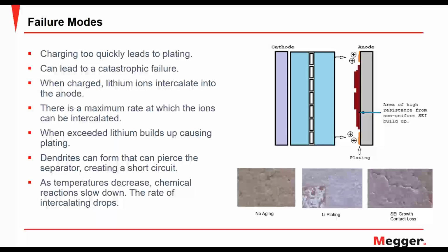This formation is caused by maybe charging too quickly. Using a maximum charging rate at different temperatures could really accelerate this reaction.